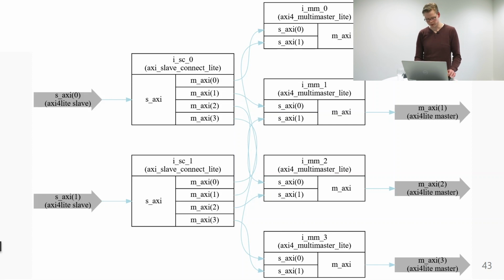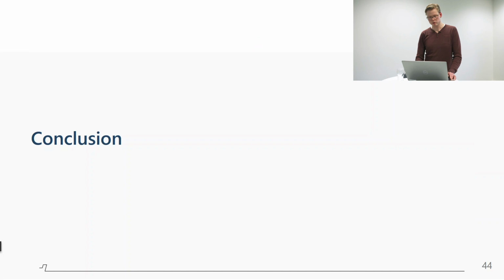This Merlin tool is something that we are actually quite proud of because it really saves a ton of work. So to conclude, basically at Prodrive we updated our whole FPGA design flow in some ways that are basically industry standards, such as using UVM and also using formal verification. But we also did some things that I think are not standard, which is, for example, use Bazel for the build flow and then also make sure that it's a fully integrated system, which is not just building, but also allows you to easily debug test benches, for example, to make sure that everybody's actually using this. And also Merlin is, of course, a good example.